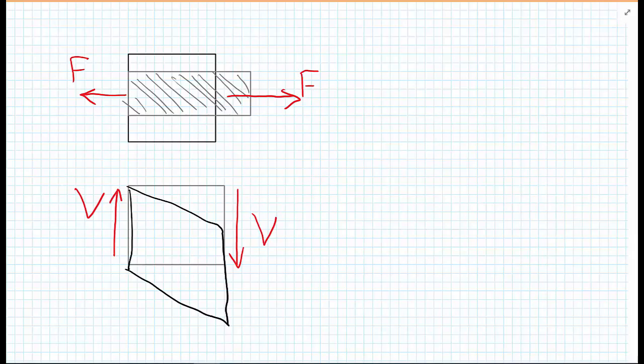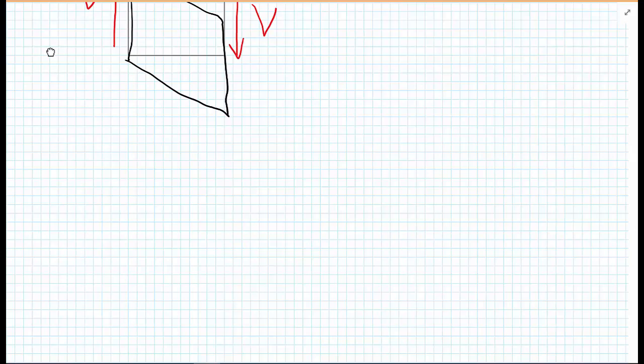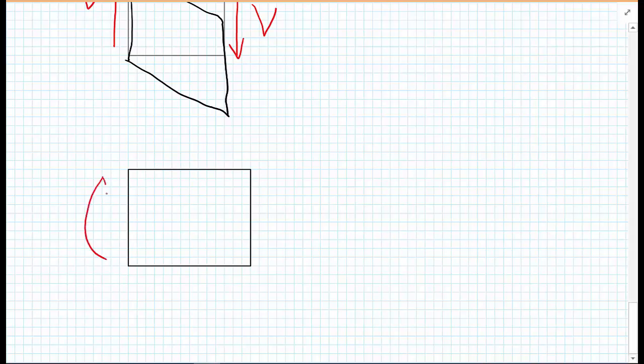And again, we'll have a look finally at the other one that occurs in 2D, which is bending. And if we apply a moment to this block, all that will happen is this block will spin around and around in circles. The block will keep its dimensions, so there'll be no change of shape to the block. However, if we now apply an equal but opposite moment, and we tend to use M, which is kind of confusing.